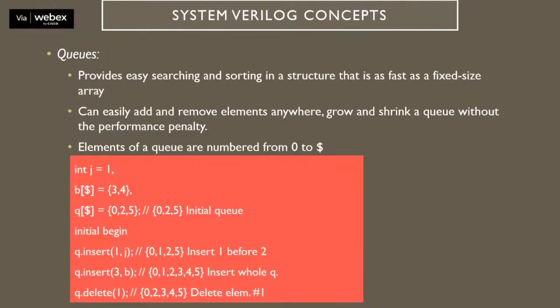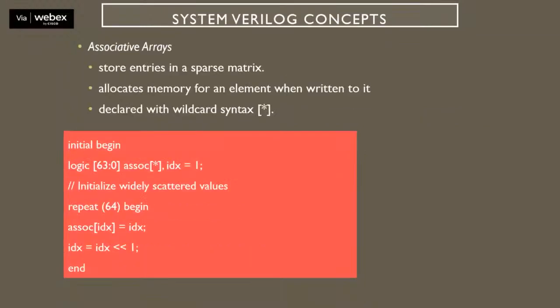Now again, if we want to move data from a fixed array to this one, can it be done? Yes, it can be done. Since the elements in the queues are stored continuously in the locations, it makes it easy for adding, deleting and also push and pop of elements. If you want to copy the content into the queue, yes, you can copy the content from the dynamic array or from the fixed array into the queues. You can do it. But once the size of the queues increases, then the timing will also linearly increase.